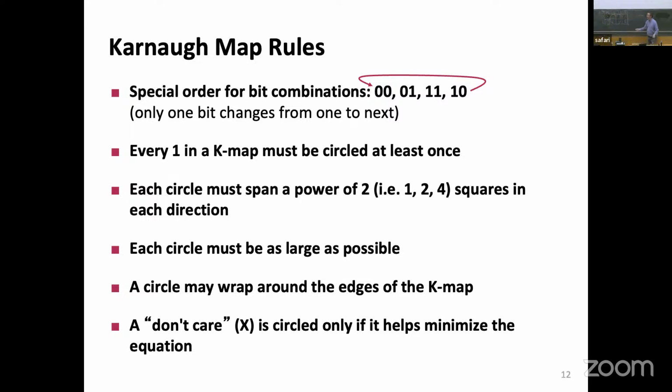And now we realize that I have the case where C is 0. B can be both 0 and 1, so B doesn't play into this. So it is not A and not C. Now, this is optimized. It can't get any better.